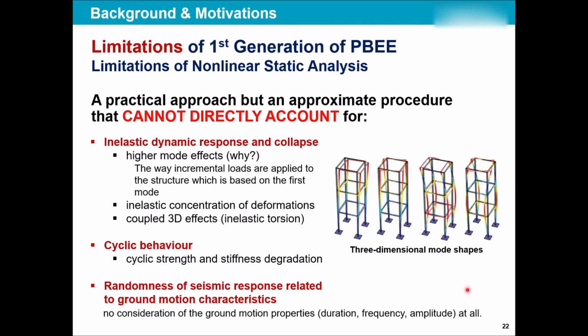Another limitation was that so far we were talking about static pushover analysis, where I have the structure and I'm just pushing it in one direction. Is this really a correct way? Remember, this pushover that we do is kind of replicating the first mode of the structure. The first mode, usually, if you remember, is a translational mode, where the building goes completely to its right, or completely to its left, or forward or backward.